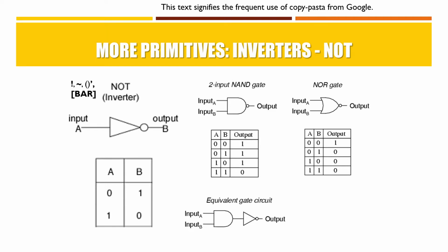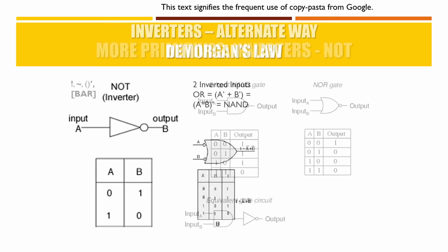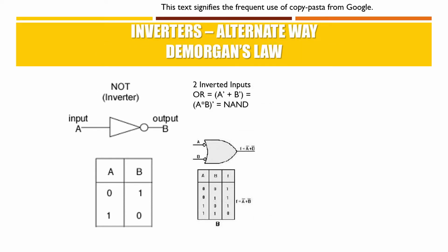circle as an inverter. And to demonstrate this, we're going to take our OR gate and AND gate and invert the inputs. Even though you would expect the OR gate to be a NOR gate by inverting the inputs, it actually does the opposite. By inverting the inputs, I'm actually changing it into a NAND gate. And if you go through the logic, let's say for example that I took 1 1 as my signal, then I'm going to now put 1 1 through the inverters, and that means that my 1 1 becomes a 0